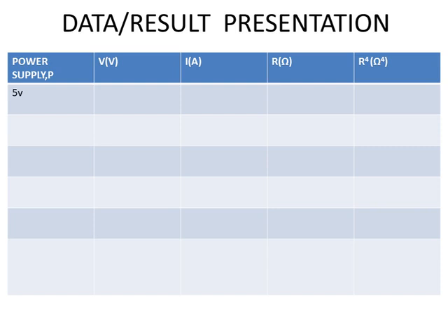By the time you close your switch, then you check the voltage on the voltmeter, you check your ammeter for the current. From the values you're having for your V and I, you get your R, which is the resistance. After getting your resistance, you get your R raised to power 4. So you do that for the other variable power supplies that you make use of. You make sure you complete the table.